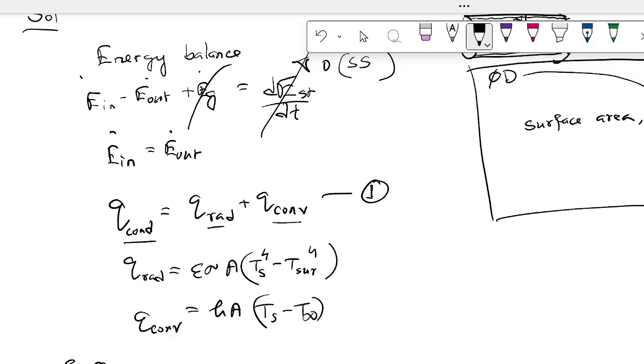Okay, so let's begin with the unit conversion. So the meter squared Kelvin to the power 4 goes away, so we're left with only watt, right? The same thing here, meter squared and Kelvin go away, so only watt is left. Do the math, and you're going to come up with a value of 18,405 watt, and that's your heat loss, or heat rate, from the pipe.